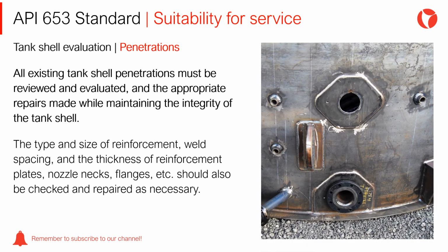All existing tank shell penetrations must be reviewed and evaluated, and the appropriate repairs made while maintaining the integrity of the tank shell. The type and size of reinforcement, weld spacing, and the thickness of reinforcement plates, nozzle necks, flanges, etc. should also be checked and repaired as necessary.